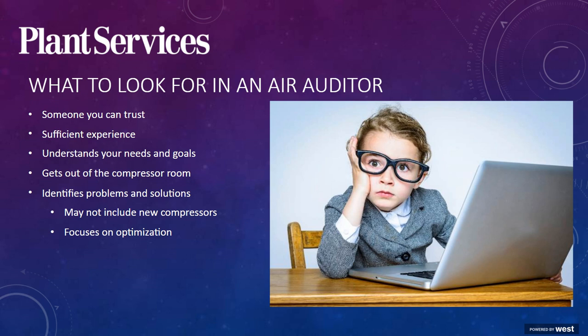So if you're bringing in an outside party to perform this service, make sure your vendor is not cutting corners and that you understand these things. Number one, what's the goal from your air demand analysis? Such as, do you have low pressure points in the plant? Do you have air quality issues? Also, figure out the necessary steps for a vendor to provide an accurate system snapshot, as well as the importance of controllers in any optimization plan. And finally, know that systems can always be improved, even with new compressors.